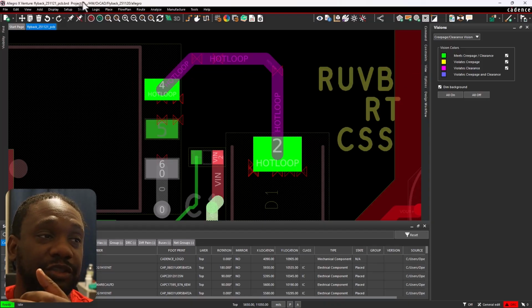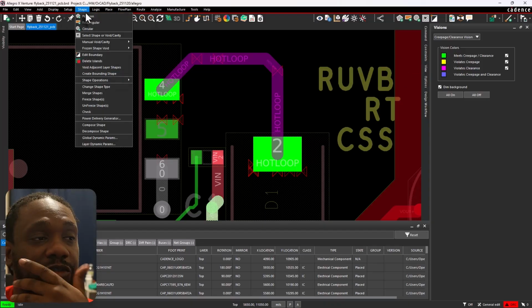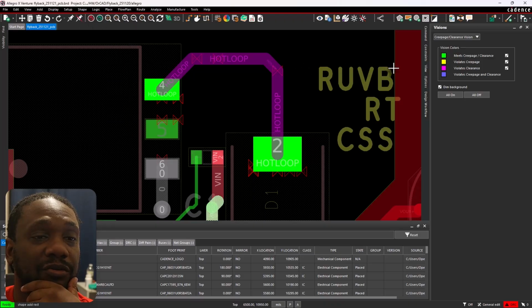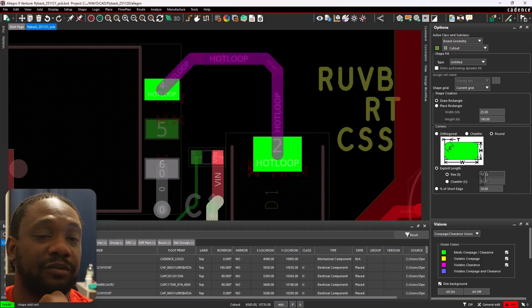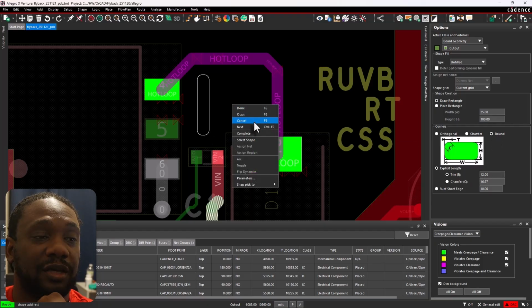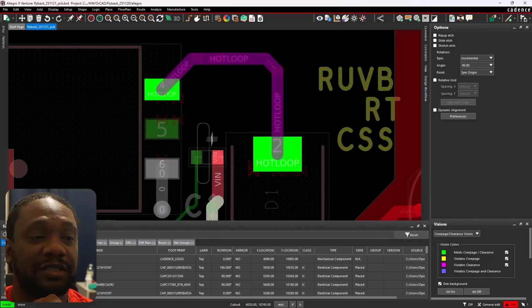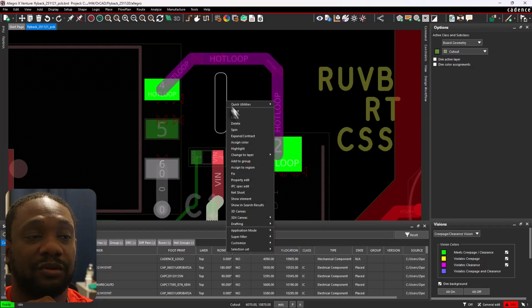Depending on your situation, you may need to place a rectangle board geometry cutout, and then you can draw a rectangle, set your trim and your rounding, then draw a slot. That would help increase the space between any of your objects.